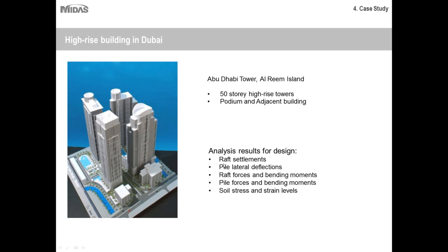So they wanted to find out what is the raft settlement, which is pretty straightforward. I mean, which is a given output. Then they need to find out what is the pile lateral deflections because of the heavy lateral loading, and then raft forces and bending moments because they have to design the raft, as well as pile forces and pile bending moments, and not to mention soil stresses and strain levels in the soil.